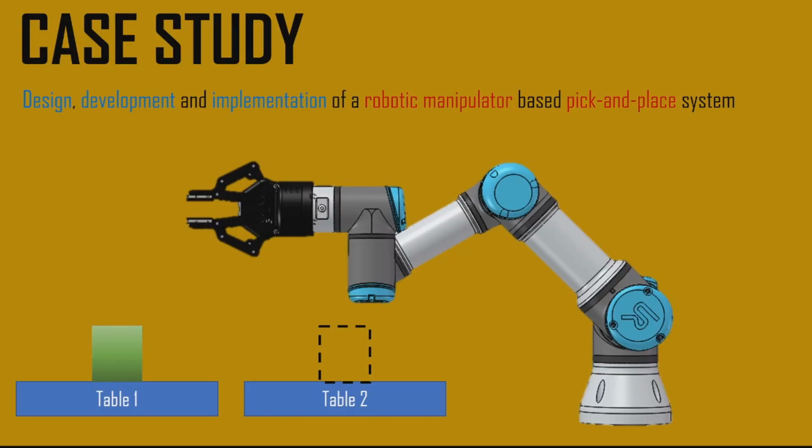camera mounted on the top of the table, what we'd be doing is we'd be collecting sets of data and actually training a machine learning algorithm that would be able to then identify or detect the object on the table, and from that position, whether it be a 2D position or a 3D pose estimation approach, we'll be able to get the position and orientation of the object, and then from that information we get the grasp pose where the end effector should be moving, and that way we'd be able to define the trajectory.